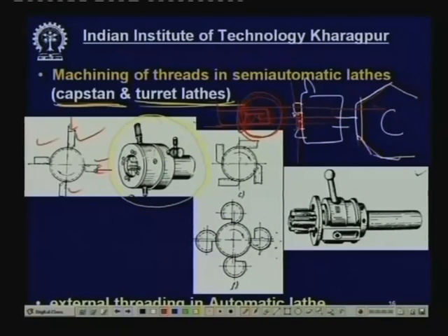Now, these cutting tools can be radially fed, or tangentially fed. These two are flat type, and this is circular type. So, there are different types of tools, and all these cutting tools are placed inside, and are moved forward towards the center simultaneously, manually by this handle, and after it reaches the end, it automatically opens because of the force. So, this is the self opening die, which works a little faster than other dies.